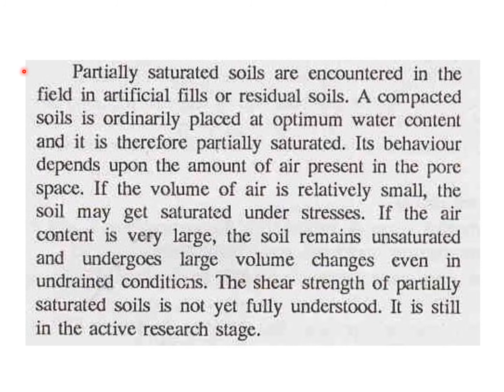Partially saturated soils are encountered in the field in artificial fills or residual soils. A compacted soil is ordinarily placed at optimum water content and it is therefore partially saturated. Its behavior depends upon the amount of air present in the pore space.